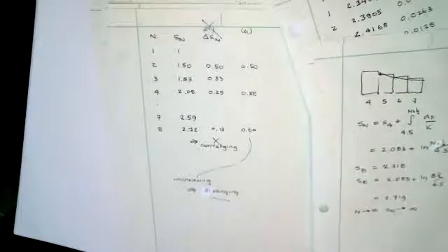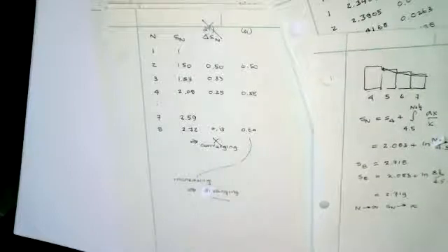So you want it to match up with your analyticals. And you will have stresses that diverge. They're called stress singularities. And you want your convergence check to say, you're not getting this stress. In fact, you'll never get it. And you'd like to learn that as fast as possible, so you stop computing it. When you have a stress that goes to infinity, first of all, as I said earlier on, quantitatively, that number is useless.